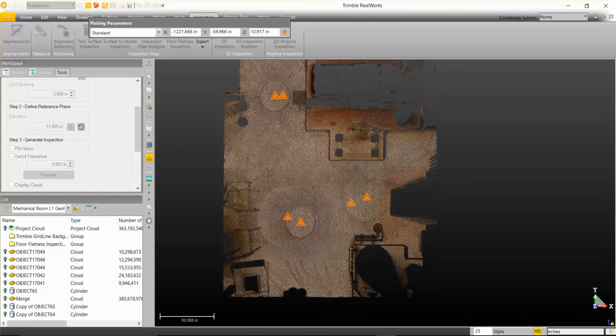Say, for example, we had poured a concrete floor and let the concrete cure. I can do my initial scan, pick, say, the top left hand corner of the point cloud, and run my analysis. Then I could come back, say, in a couple of weeks when the concrete is cured, pick the same reference point, and again it's going to compare those 2 points. So if there's any difference in the concrete over that time period, you can compare and contrast both results.